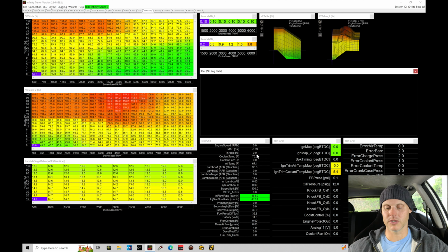So just as we always like to check, the MAP sensor is calibrated right. Now I'm at sea level, and it's just showing approximately 0 PSI, key on engine off. At sea level, that's exactly what it should be reading, so the MAP sensor looks good. Normally, this is going to be a critical factor in making sure that the load input to our table here is correct to the VE calculations, but in this case, throttle position is now used. So throttle position is actually just as important, if not more important, in this Alpha-N strategy to make sure that this is calibrated right.